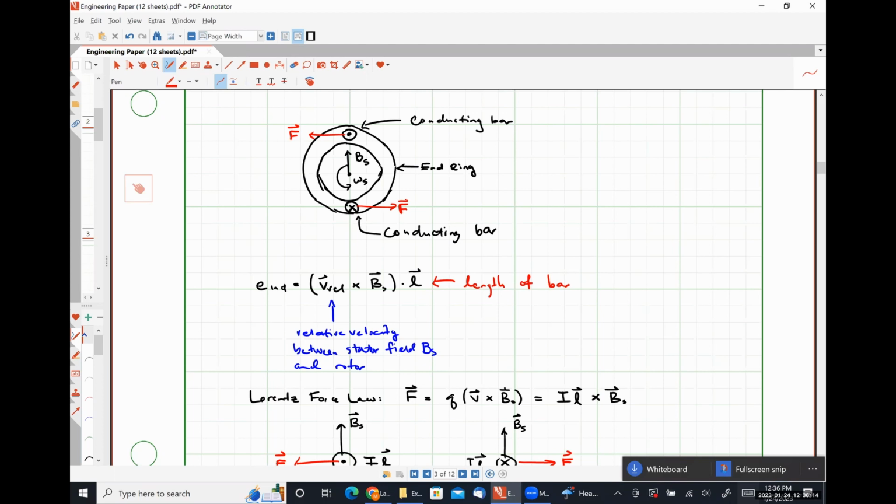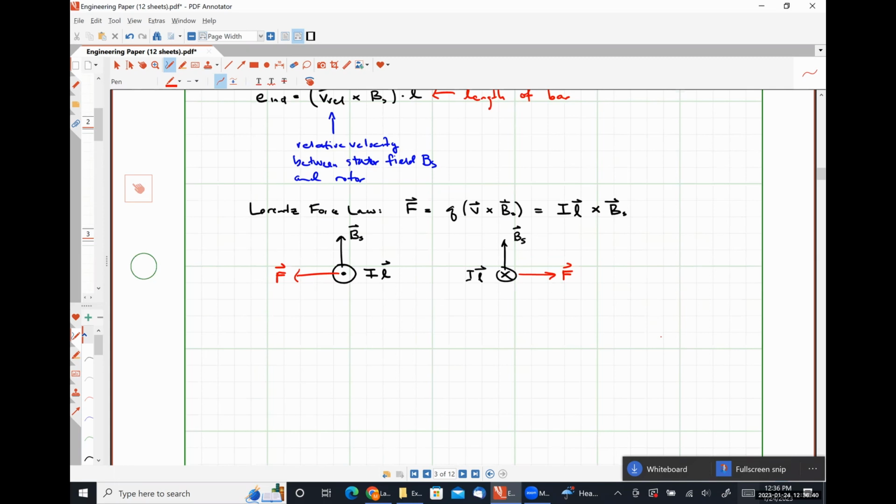So if our B field is spinning at some particular speed, the best the rotor can do is the same thing as the B field, right? It'll never get past it. If it ever gets past it, that means we've had to add mechanical power to cause it to speed up and overpass it, right? So the fundamental limitation of our rotor speed is our stator speed effectively. So this is one of the relationships that I gave you guys in that PowerPoint lecture.